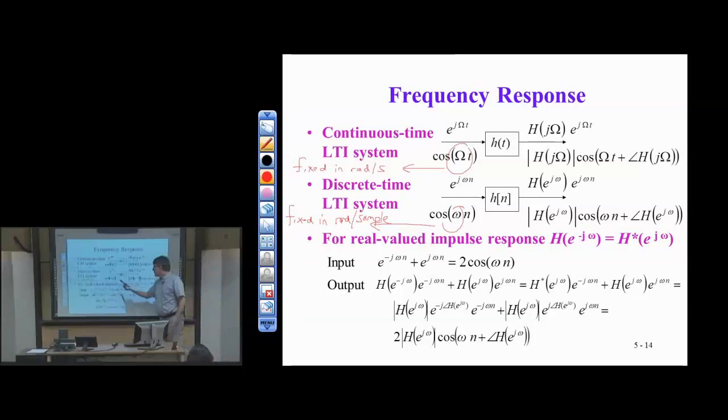Now, lab 3 will send a cosine of finite duration through and see what happens. And you know from homework that if I have a finite duration cosine, then I have a lot of energy at this frequency, but I also have other frequency content, but it drops off or decays pretty quickly. But you'll see a very similar phenomenon: you can put in a finite cosine, and you can look at the output and compare the two on the oscilloscope. If you had to do it with rack equipment, you would manually estimate the change in the magnitude and the change in the phase by superimposing the two signals.